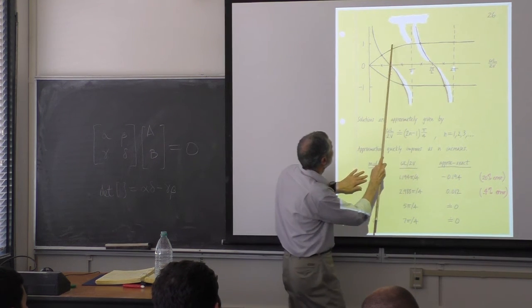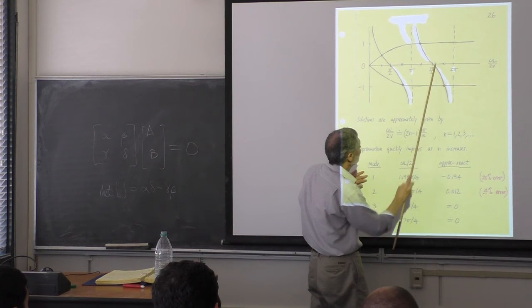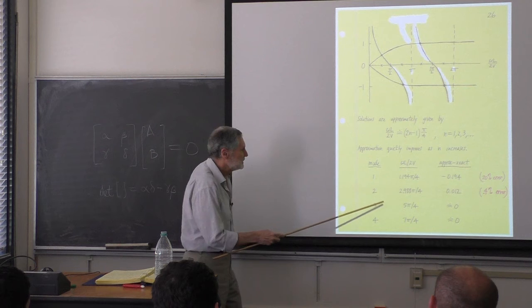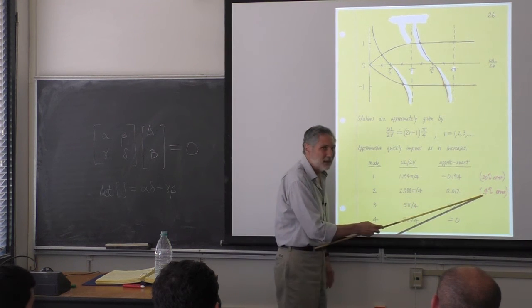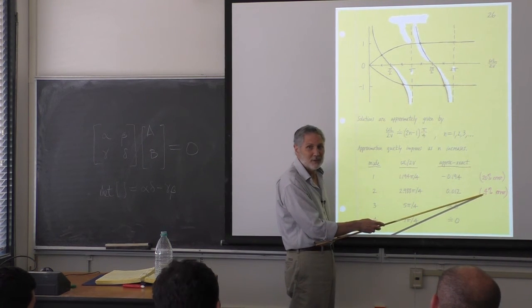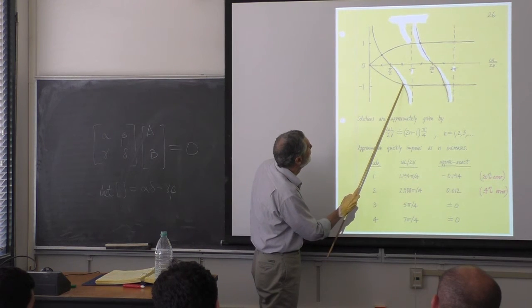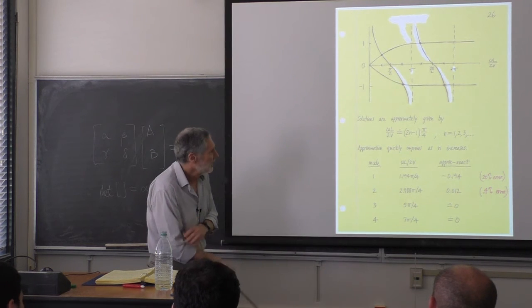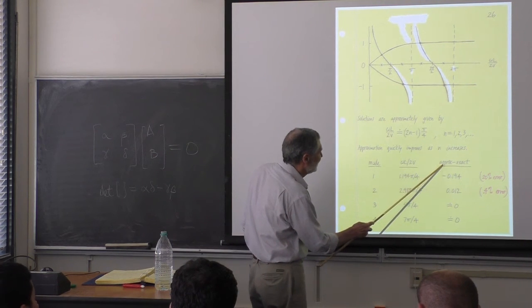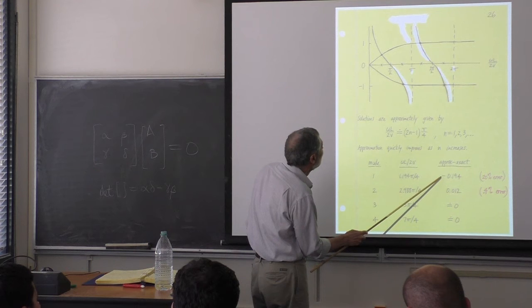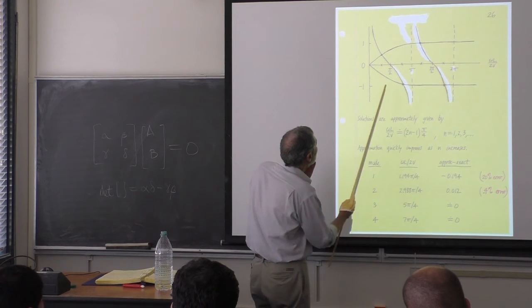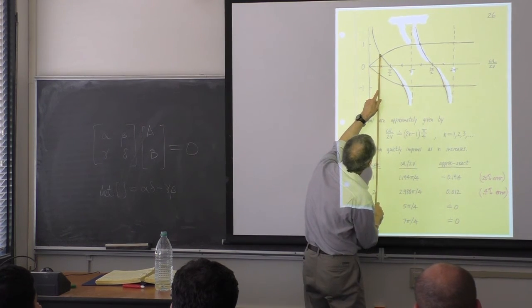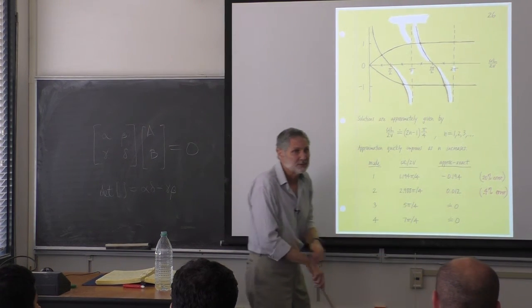The approximation here of just setting the hyperbolic tangent equal to plus or minus 1 works extremely well from the third mode on. It's not bad for the second mode. It's roughly 0.5%. It's less than 1% error for this mode right here. That's not bad. For the fundamental, though, it's about 20% off. And you'll see this is the approximate value minus the exact value. And you can see here that our approximate value, if I had drawn this more carefully, would be right about there. It would be less. So we confirm that minus sign in.